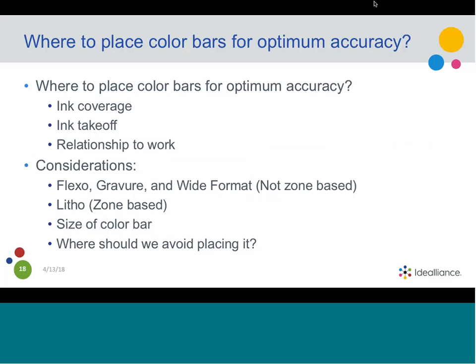Ron, I'll turn it back over to you to talk about where to place these color bars. Yep, so placement of these becomes really, really important. And, when you talk to printers, one of the first mistakes that you see that brands make is they basically start popping these color bars all over the place. And if those color bars live in a gutter or someplace where there is no ink coverage or takeoff, then you end up with something that doesn't actually relate to where the printing really is.